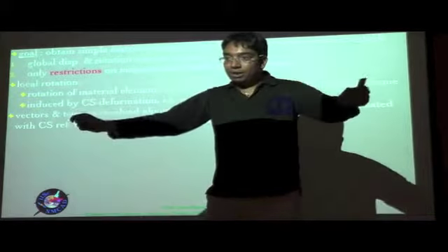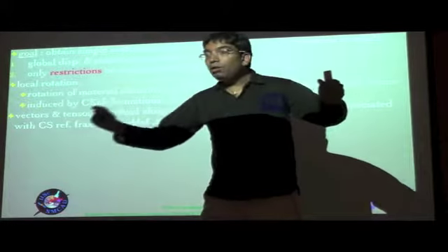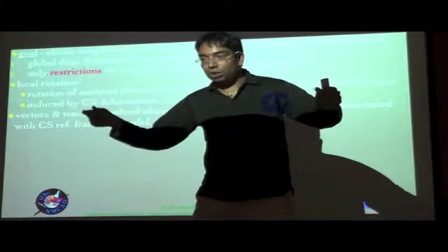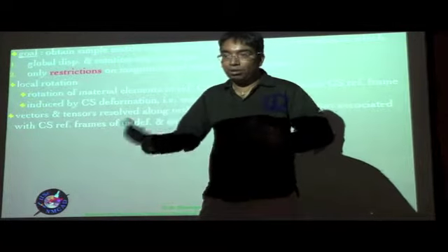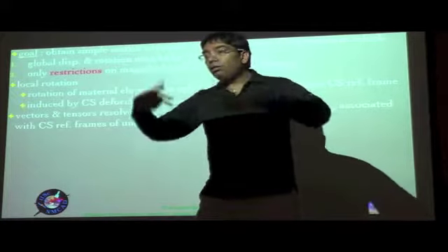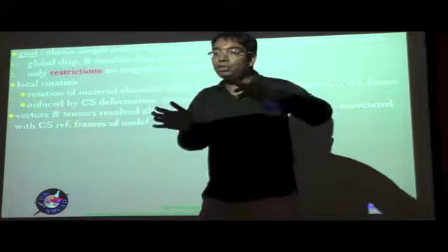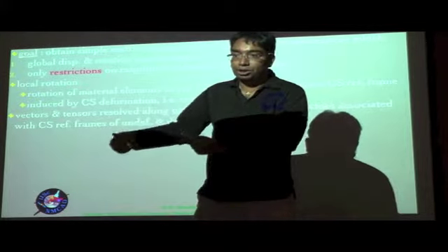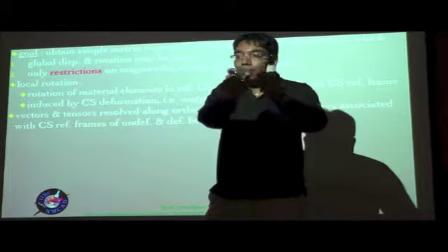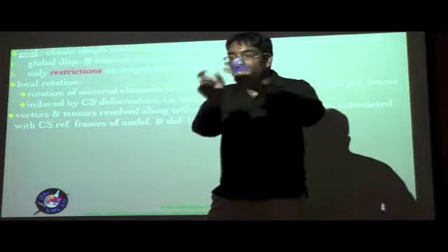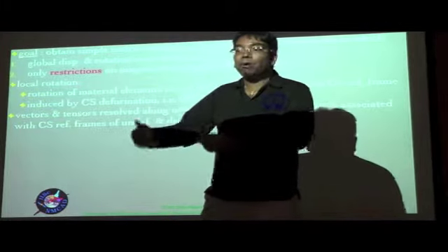So from that expression itself, because the total strain has to be small, we can determine the order of magnitude of those local rotations. So that will enable us to estimate the orders of magnitude. And of course, those are unknown quantities, which we will solve for when we get the governing differential equations using the Euler-Lagrange equations of the calculus of variations. When we solve for them, we can go back and compare with the estimate that we made for the local rotations, and then arrive at the appropriate conclusions.